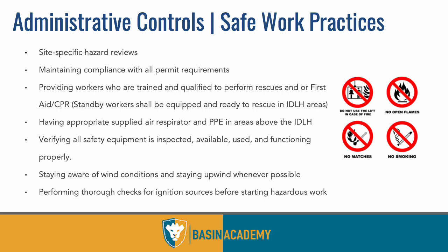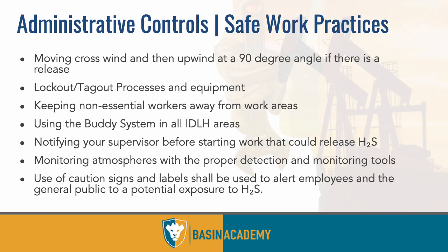And then as well as inspecting your equipment, making sure people are standing upwind at all times, no matter what, even if they are under air. Prevent the exposure as best as you can all the time. So safe work practices, again, communicating with people, having a buddy out there. Like, hey, I'm going to drive into this area where we know has H₂S. If I don't call you in 15 minutes, send somebody. There's gas monitors that if you fall over on your side and are inactive for so long, it'll send out a signal and people will come for you. There's a lot of unique administrative controls out there.